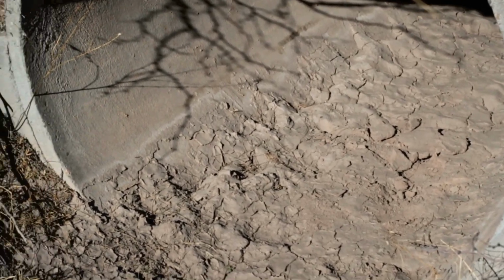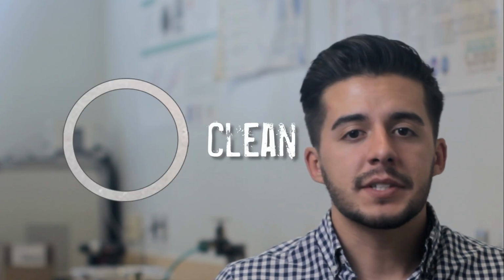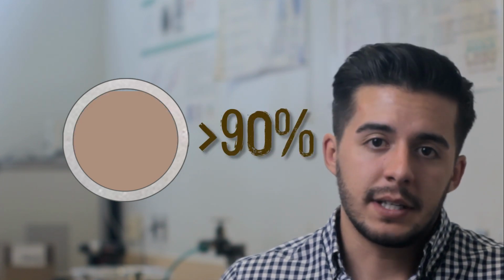Finally, but not least, siltation occurs when the carrying capacity of flowing water is less than the amount of silt being carried. A culvert can be completely clean, or it can present minor silting if it's less than 10%. It can have 10 to 30%, 30 to 60, 60 to 90, or more than 90% of silting.